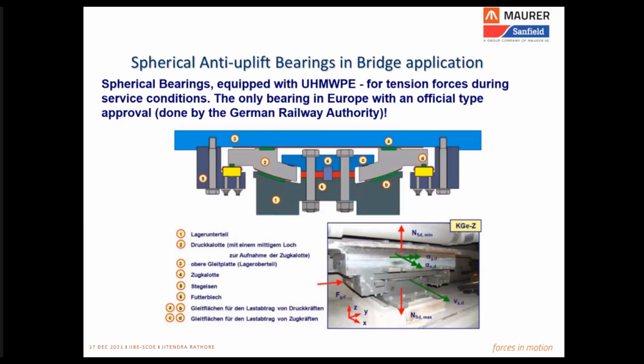Here it is also important to understand one simple but decisive fact: the uplift is to be first understood, whether it is a simple seismic uplift or a service uplift. If the bridge has a seismic uplift requirement, that means the uplift is only expected to come when there is an earthquake.